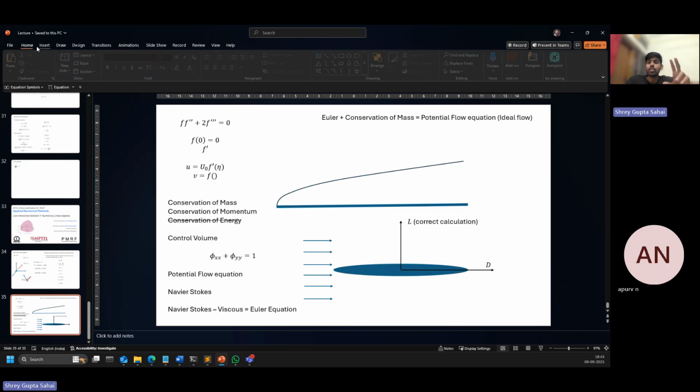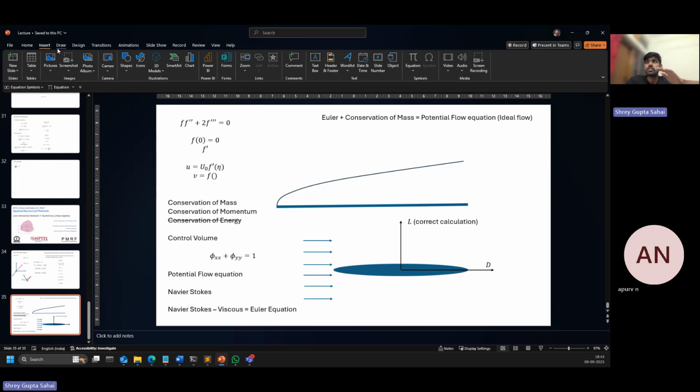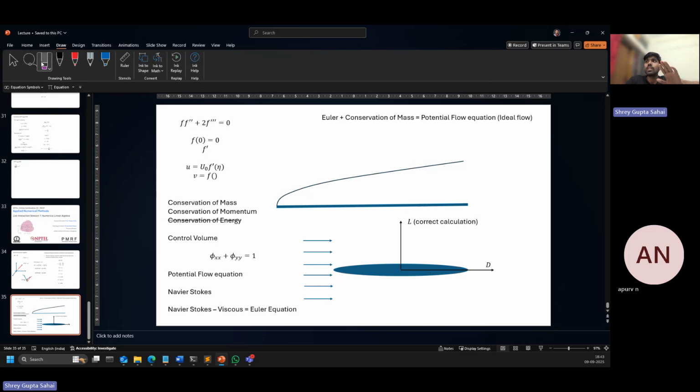What he did was he postulated that it is not that the flow is entirely inviscid. It is important for us to consider the regions very close to the wall, because it is where the effects of viscosity are so important that they overpower, or are sufficiently high to affect the velocity, or the drag, or the skin friction forces.